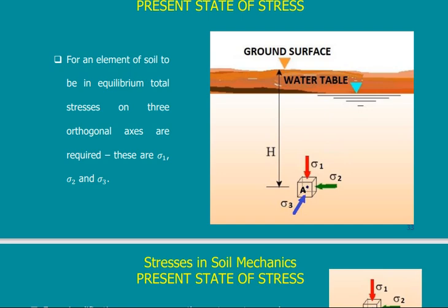So at any point, what concerns me are two things. Actually, they are one thing. What is this one thing? The length of this column of ground. If I have a point here, above me there is ground. What is the depth of this ground and what is the unit weight of this ground?